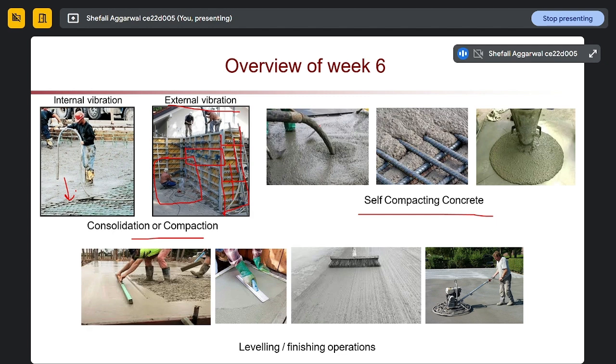In this method of classification, we classify cement as ordinary Portland cement (OPC), then Portland cement with low heat, rapid hardening cement, pozzolana cement, or slag cement. Also in these different types of cement, we will have different compositions of compounds present.